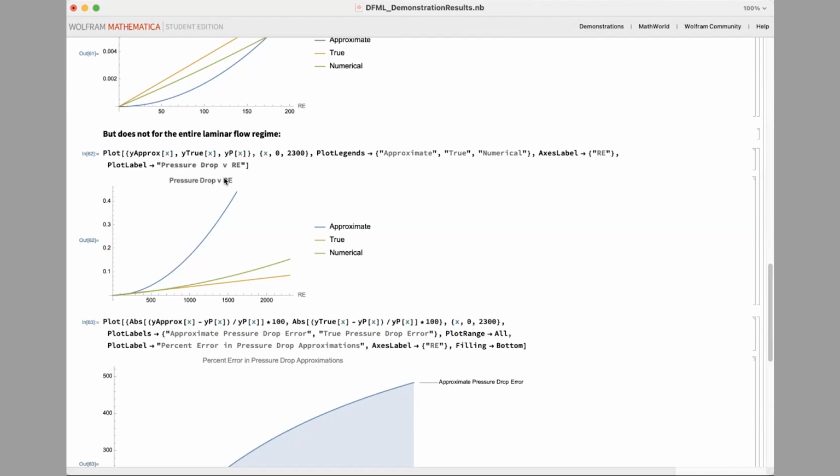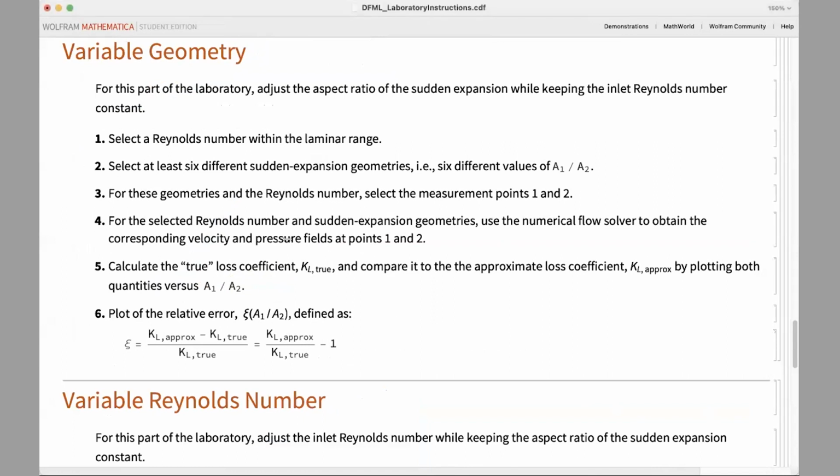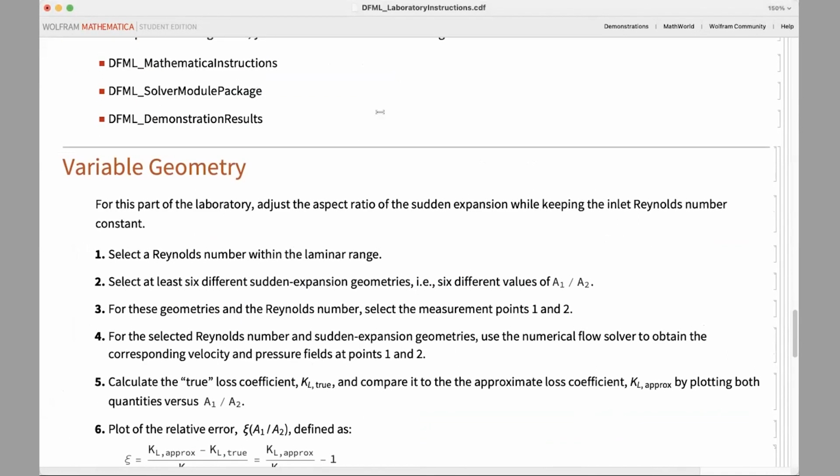Okay, well, in this fitting, can you go to one of the meshes we have? Is it by accident that you have denser meshes around the boundaries? No, that's not by accident. Let me jump over. Wrong screen, sorry. So what we're getting at here is that you want to be refining the boundaries, because we want to show that we're satisfying our boundary conditions.